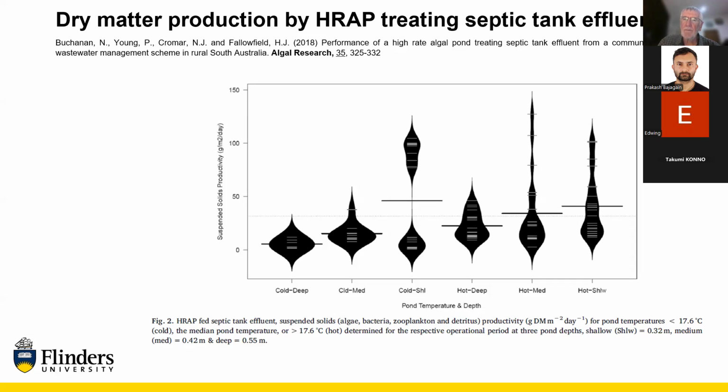The evidence from other research is you can't economically treat wastewater in a photobioreactor by inoculating with a defined algal strain, because you can't keep that. You will always have algae come in the wastewater, and you can't keep that monoculture of algae.